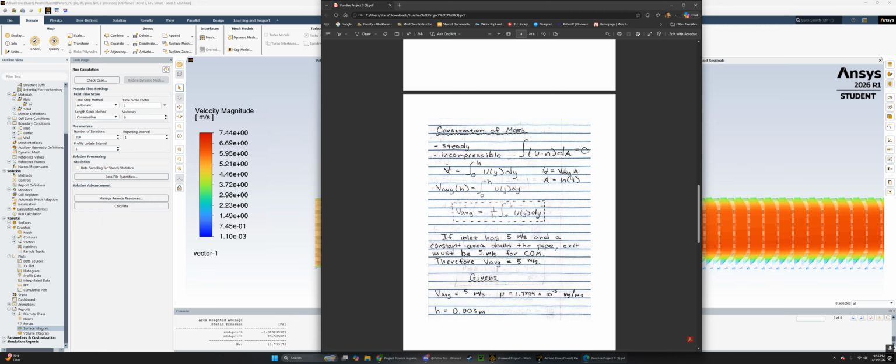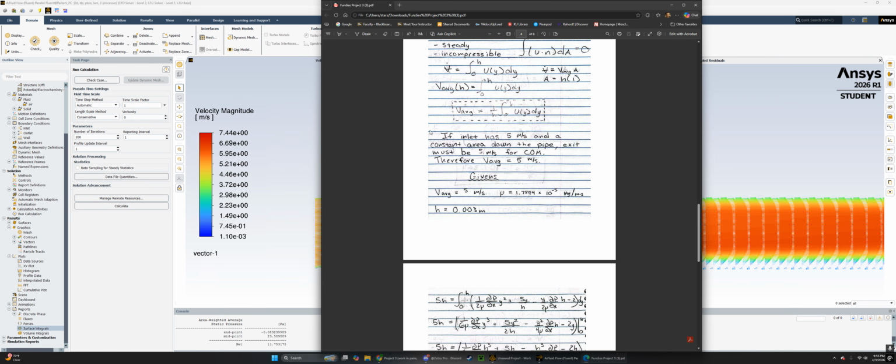The volumetric flow rate equation is velocity times area. So we know the area is h times, we're going to use just some unit value of 1 here. So that gives us our V average equals 1 over h, the integral of this, u dy, multiplied the h over here. And actually, I brought it back down over here. Okay, I see.